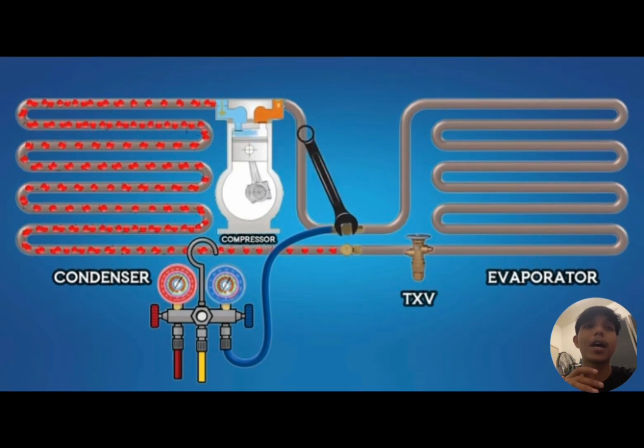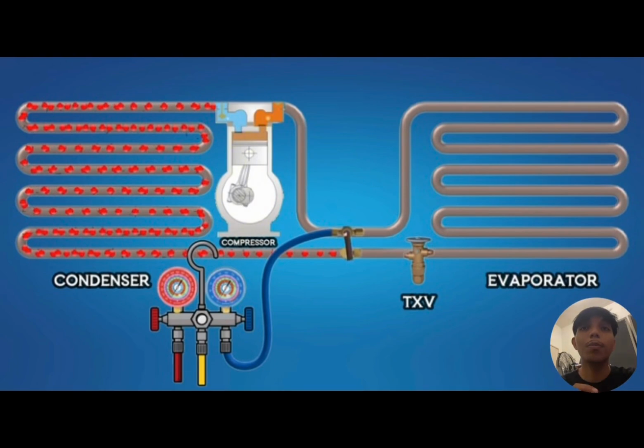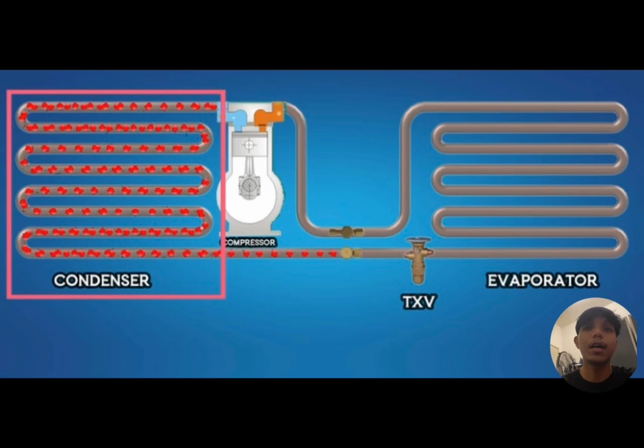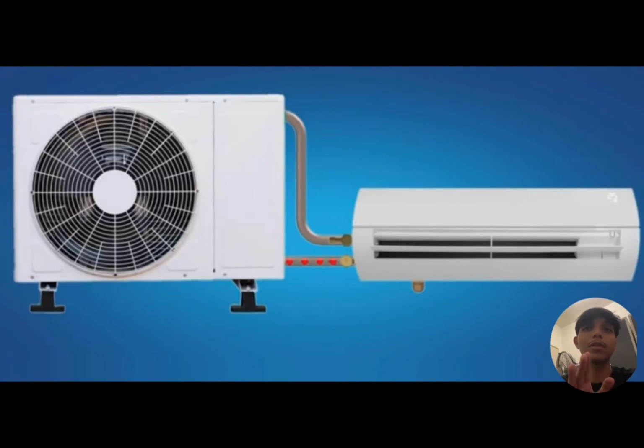When the pressure gauge shows 0, open the valve cap on the suction line and close its valve stem. Finally, turn off the aircon unit. At this point, all the refrigerant from the evaporator and coil will be stored in the outdoor unit. Now we can disconnect the coil from the service valve. Alternatively, we can proceed with any maintenance work required on the indoor unit. That's how we perform the pump down process in the aircon unit.